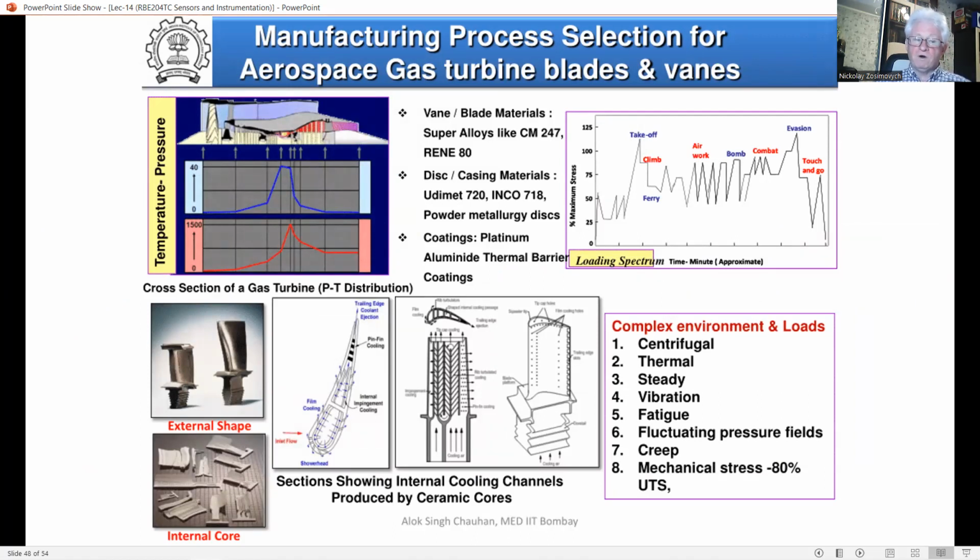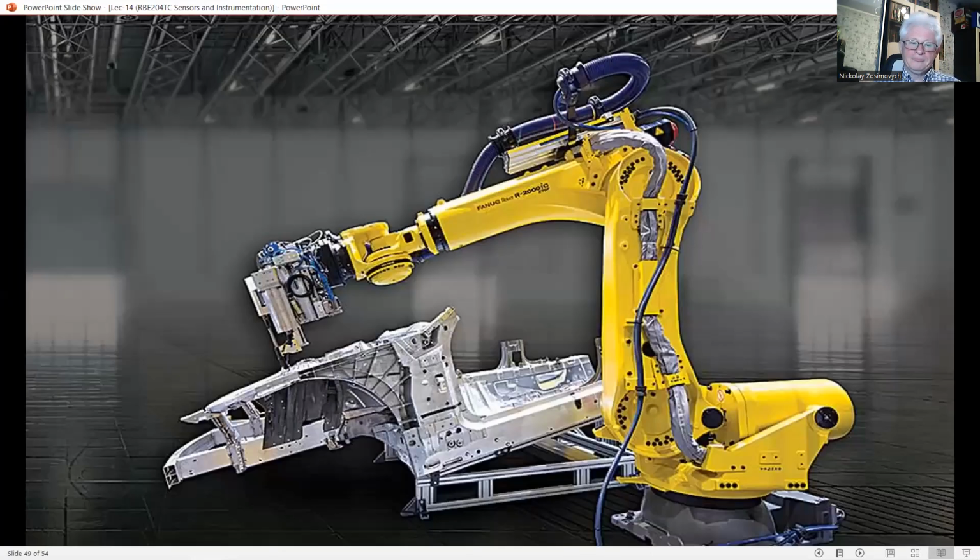Four, forge the billet into shape. Five, perform surface finishing operations to get the required airfoil shape. Six, when the surface finish is satisfactory, machine the blades through. Note that the entire task involves a sequence of events where each event depends on the completion of the previous one.